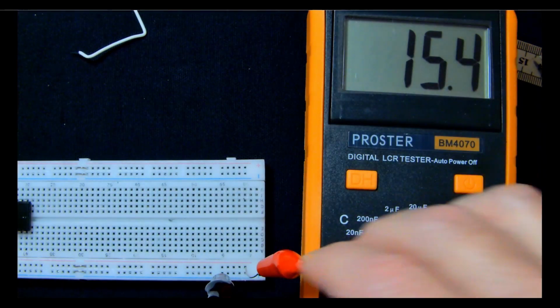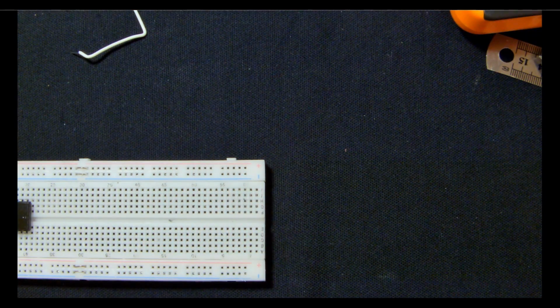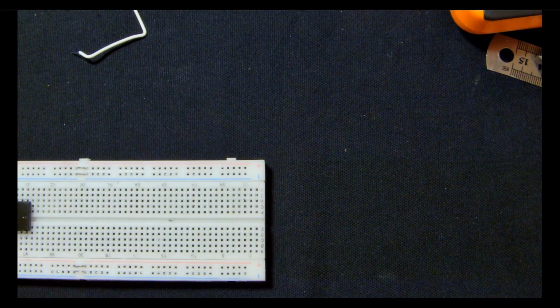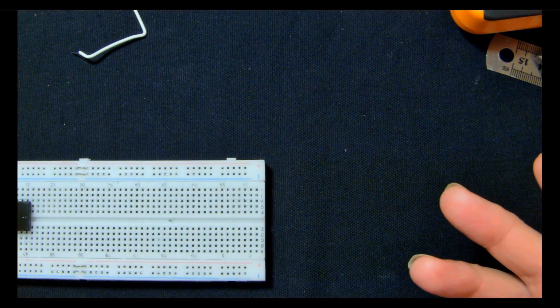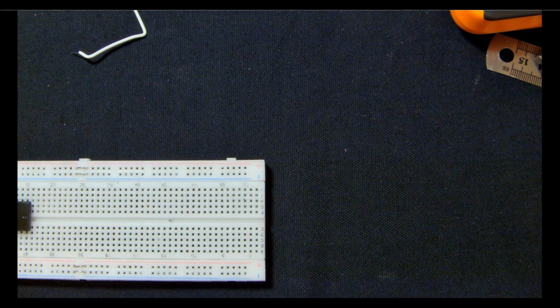So capacitors can cause a delay in rise time of a signal. It might affect an oscillator and its resonance value. So if I were to design and put a Hartley oscillator on there and just plug it into this board, then I might find I'm not getting the frequency that I'd expected. Or let's say I commissioned it on a turret board and everything was working absolutely fine, and I took those same components and put them on the breadboard and connected them up, I probably would not get the same response, and you should just bear that in mind.